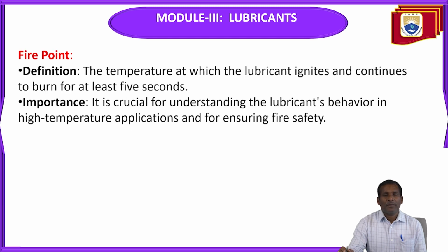Next, fire point: the temperature at which the lubricant ignites and continues to burn for at least 5 seconds. The importance is that it is crucial for understanding the lubricant's behavior in high temperature applications and for ensuring fire safety.